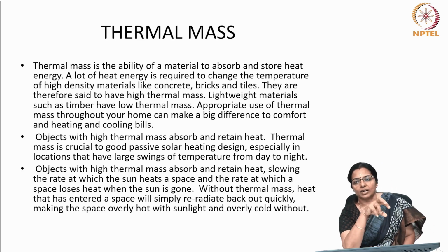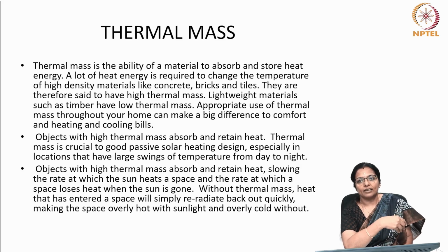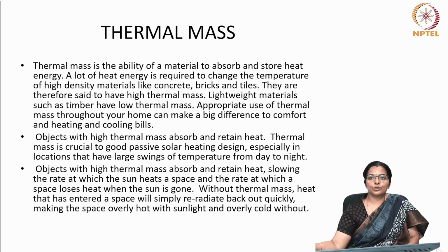So, thermal mass is the ability of a material to absorb and store heat energy. A lot of heat energy is required to change the temperature of high density materials like concrete, bricks and tiles. They are therefore said to have high thermal mass. Lightweight materials such as timber have low thermal mass. Appropriate use of thermal mass throughout the home can make a big difference to comfort and heating and cooling bills.